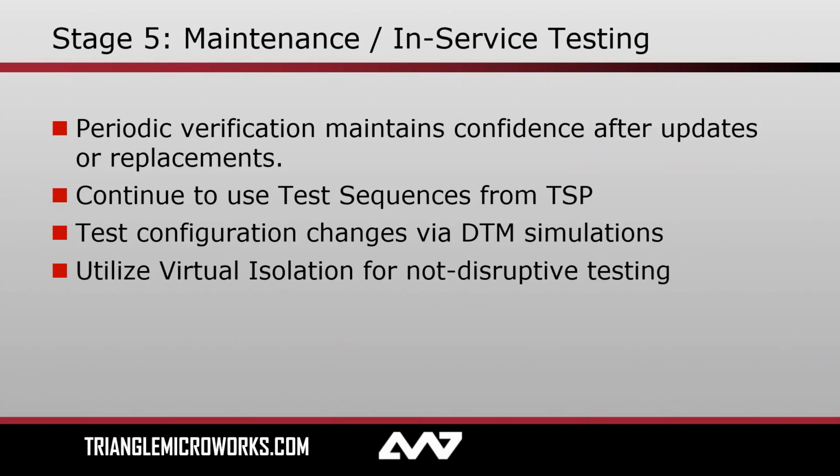Certainly if you're adding a new bay, simulation would come in handy to design and simulate your entire substation, including the new bay, and validate the communications there. But it's also where virtual isolation comes into play. And we'll talk more about this in the coming slides. This is what enables non-disruptive testing.